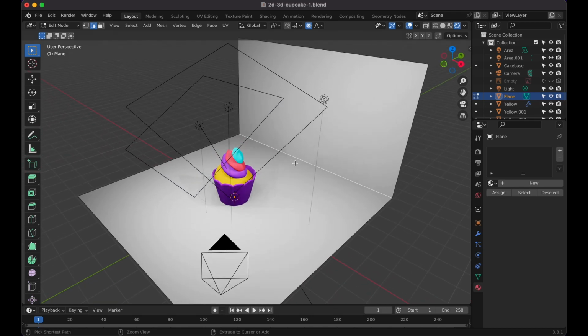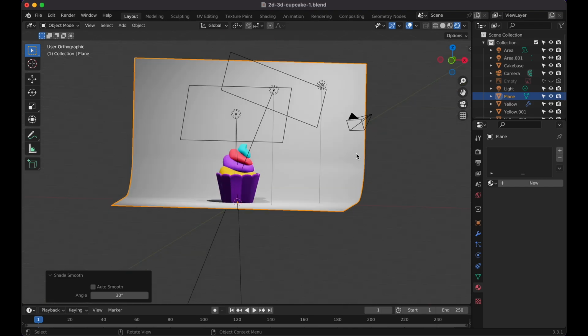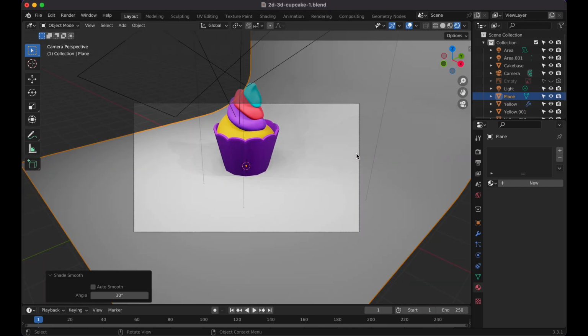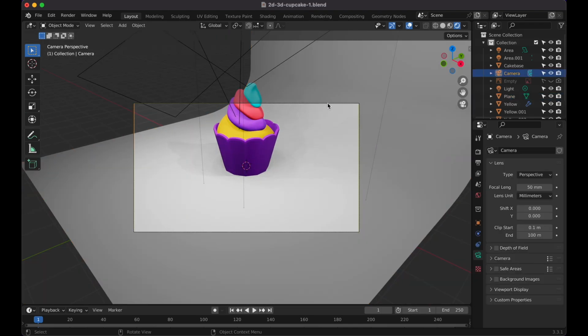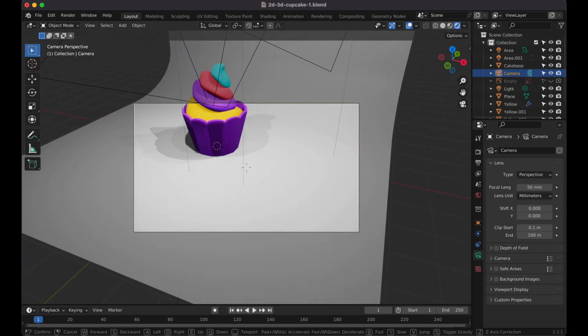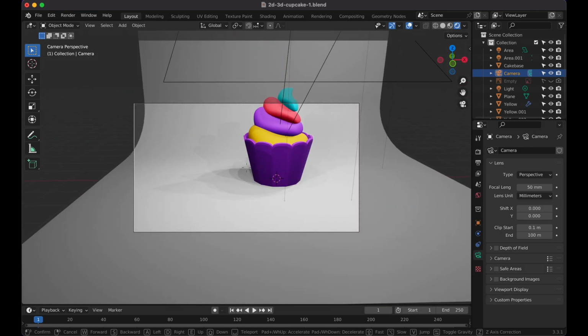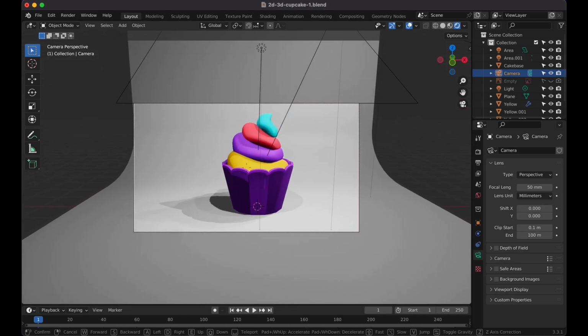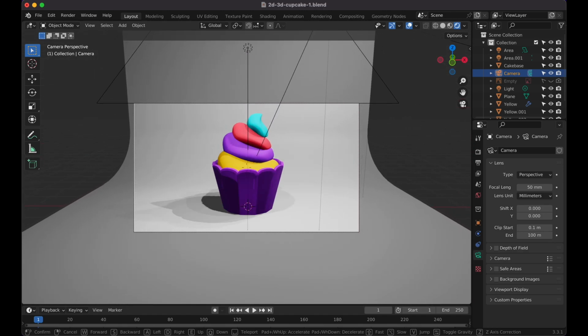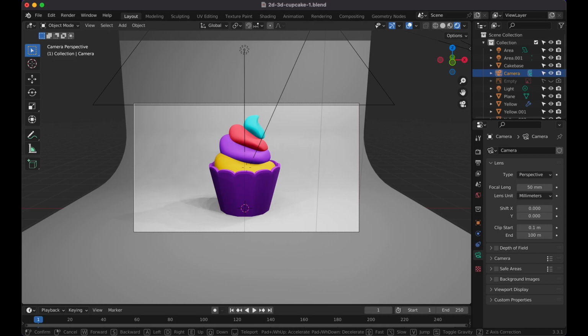And then Command B or Control B to bevel, and then just scroll on your mouse wheel or on your laptop, depending on what you're using. And basically just form a curve. Right click, shade smooth. Now press 1. Press 0 actually for the camera. Click on the outline of the camera, Shift and asterisk, and then Shift and WASD basically allows you to move it around. And by holding Shift, you can move faster. So now we have it right about here. I'll keep it right there.